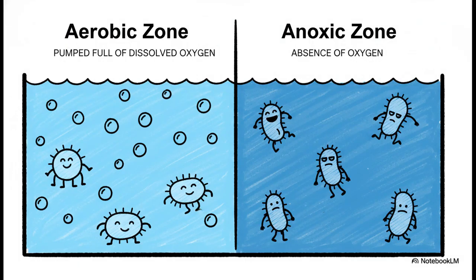The absolute genius of BNR is that it creates two totally different environments to get two different types of bacteria to do all the work. First, you have an aerobic zone, which is pumped full of oxygen. Right next to it, you have an anoxic zone, which has 0 dissolved oxygen. This whole two-zone strategy, well, it's the key to everything.